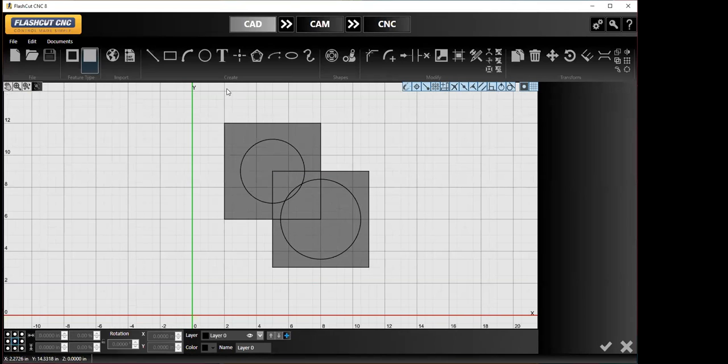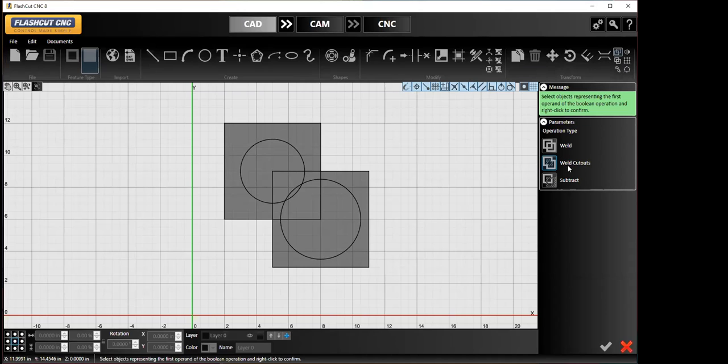All right, now this last example I will show you is the Boolean subtract option. Move to subtract. We will again highlight our parts group in the rear as our primary. We move to any line of the object and right click to turn that yellow, becomes our primary.